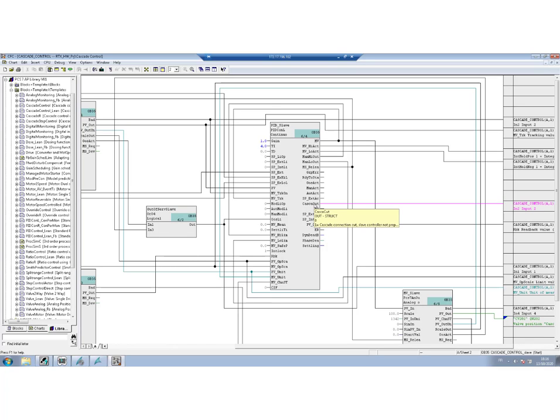And here there is an output of this slave control that is called cascade connection cut, right? So for instance, when this controller is going to manual mode or to internal set point, this one will go to 1. So as you can see, this interlock strategy has been correctly programmed in this template.